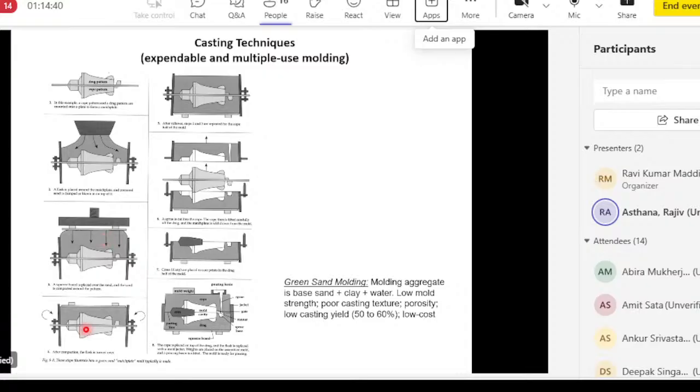Once one side is done, you flip it down and repeat these steps to make the other half of the mold. When both sides are done, you can open the mold, remove the match plate, put in any sand cores if you need to make any internal surfaces, and then reassemble the mold, pour hot metal, and once the casting solidifies, you get your final part. Weight on the top, especially if you're pouring heavy metals like iron or steel, otherwise the cope might float up.